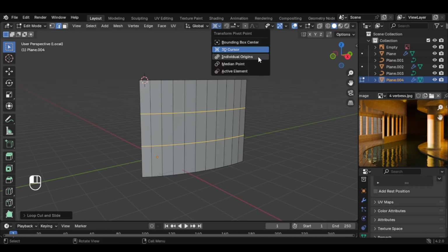So it's gonna look like this. And we also have to give it some thickness, so tap edit mode, select everything, and then Alt and E, extrude faces along normals and bring them inwards a bit so we have more thickness. And go back, and now it should look like this. And don't forget to auto smooth it.